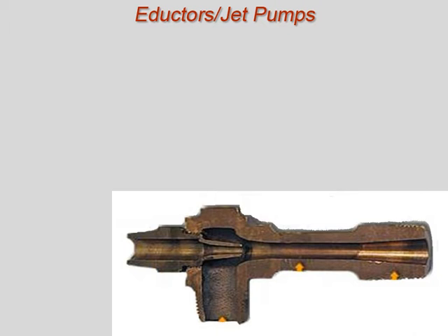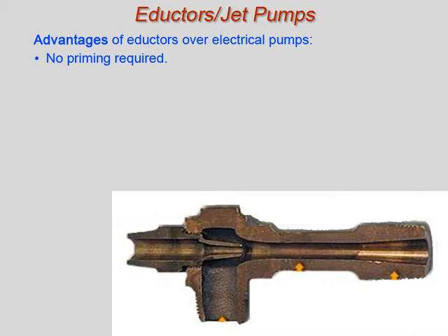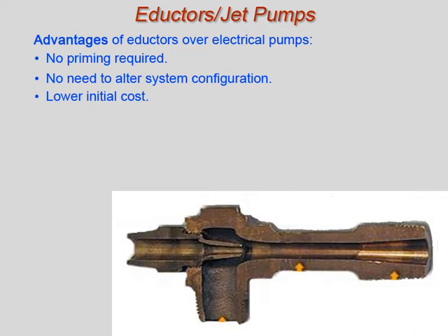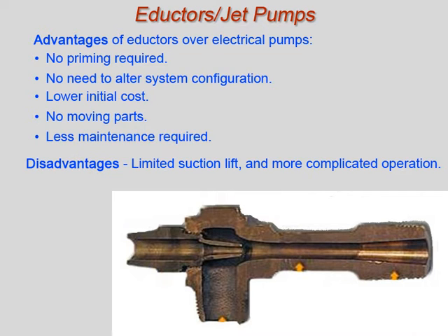Eductors are used to transfer fluids from one location to another without using an electrically powered pump. The advantages of eductors over electrical pumps include no priming required, no need to alter system configuration, lower initial cost, no moving parts and less maintenance required. Disadvantages include limited suction lift, more complicated operation.